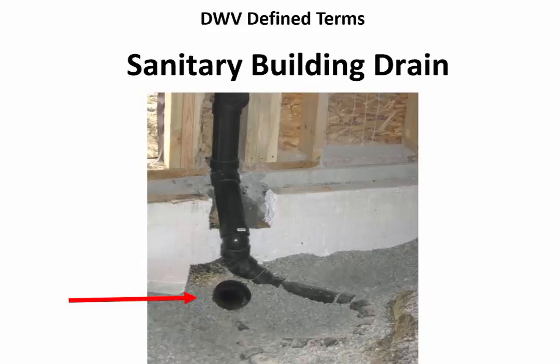Sanitary building drains are sized in accordance with Table 24.10.6c and will be a minimum of 3 inches in size. Sanitary building drains must be served by at least one vent in the system that is 3 inches in size, as per Article 2584, Sentence 5.